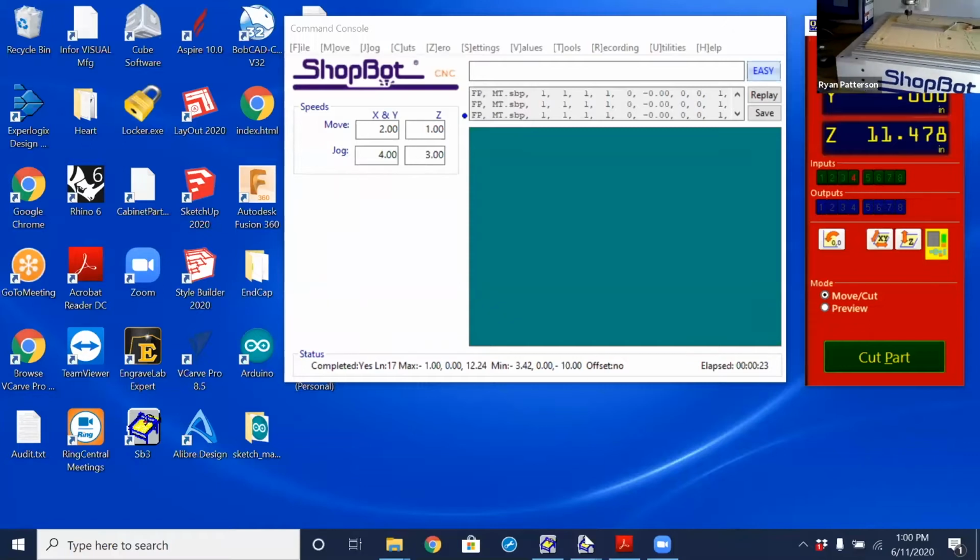So we're going to work on using a Z zero plate to check and verify what the material thickness is, by using the Z zero plate on the top side of it. Then we'll move the material out of the way and also touch off of the plate again at a different level.